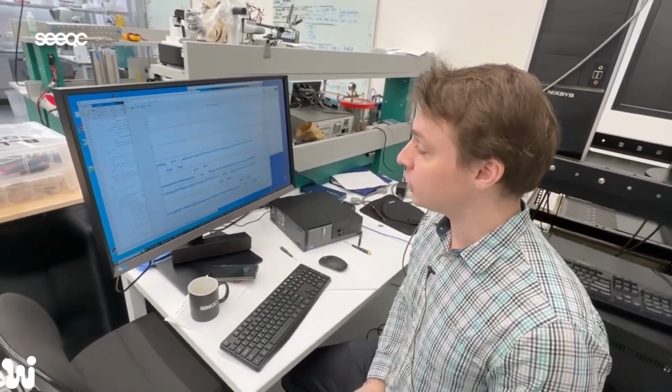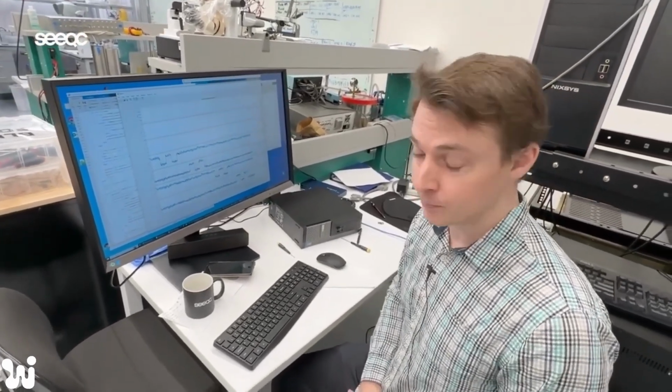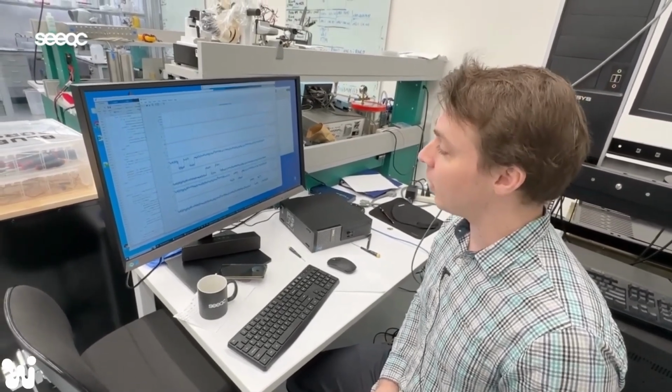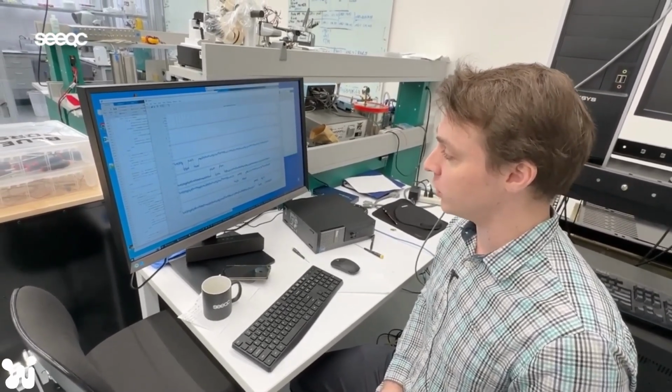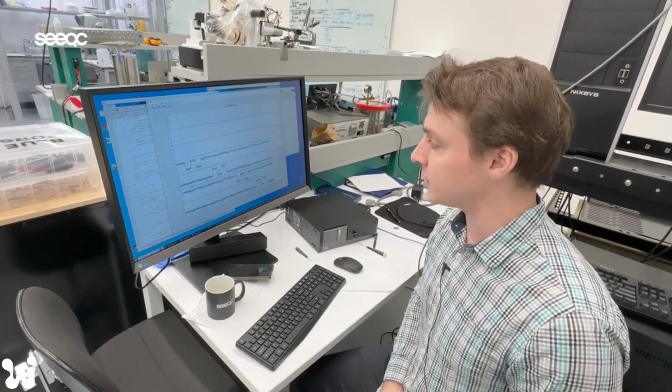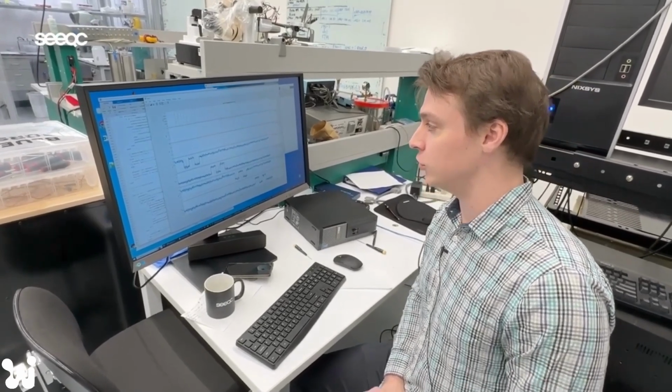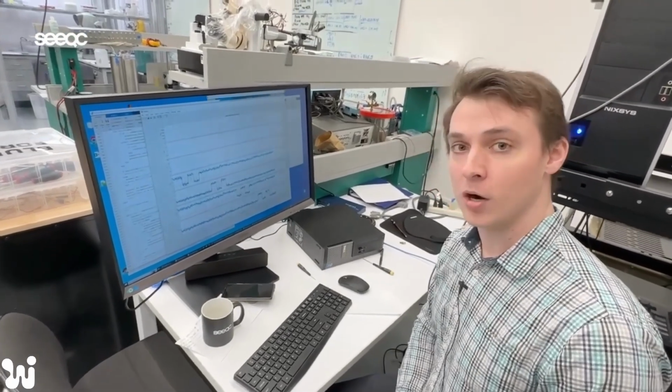This is a good working circuit, which we are then planning to use this physical carrier chip to bond with one of our quantum chips to make a multi-chip module. So I'm pre-screening at 4 Kelvin right now to make sure that our SFQ control circuitry works correctly for further testing at millikelvin and to have it talk to our quantum chips.